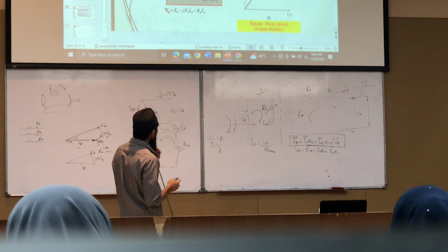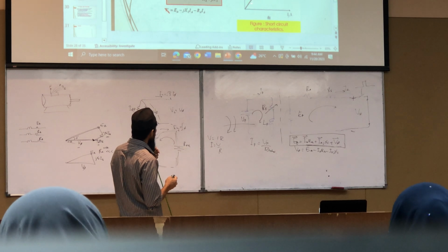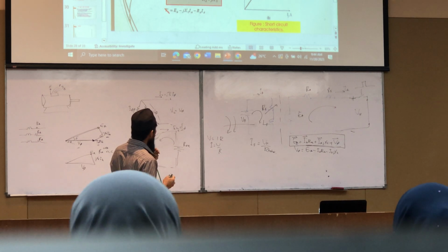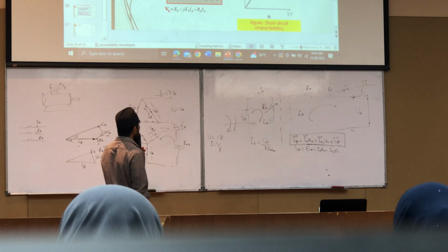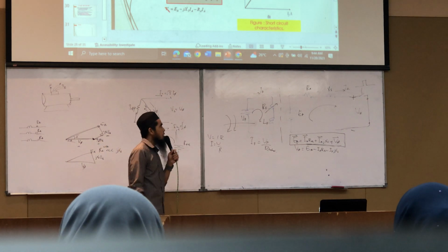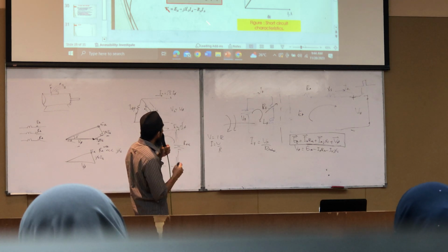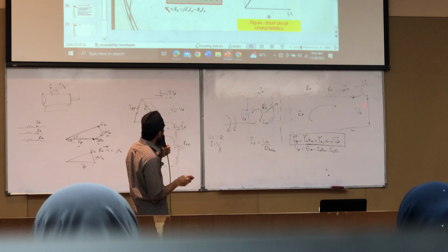So we increase the field current and perform the short circuit test, measuring at this value of field current how much the short circuit current is. And actually, it should be in the linear region. The higher the field current you apply, the higher the short circuit current you should get. Okay. Formula, but at this moment, V out is considered zero because we short circuit the output.